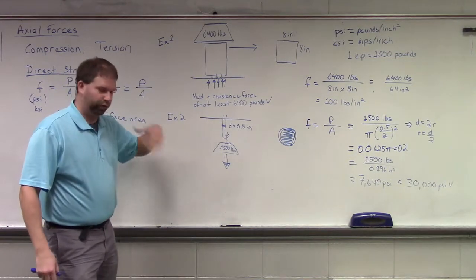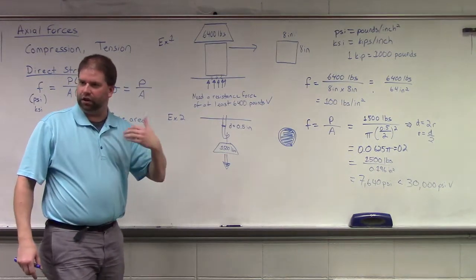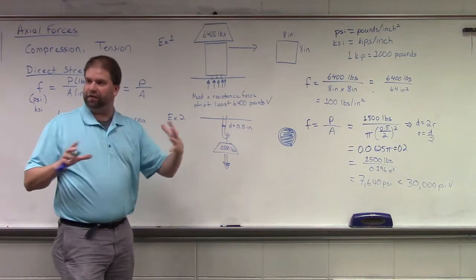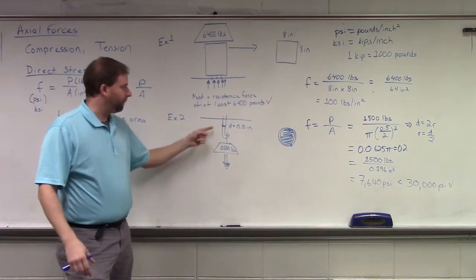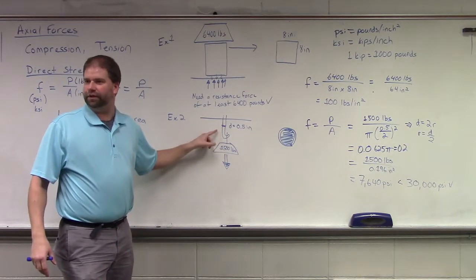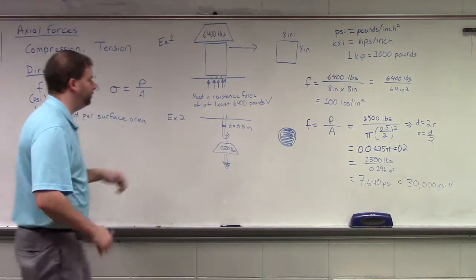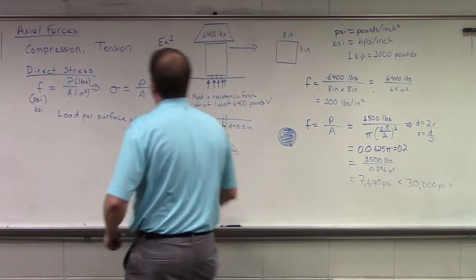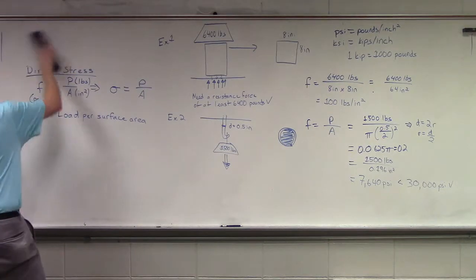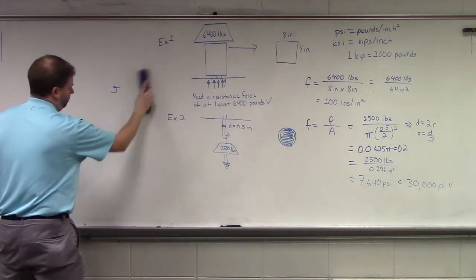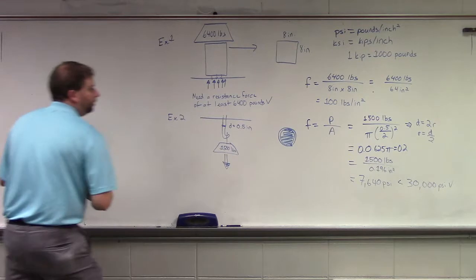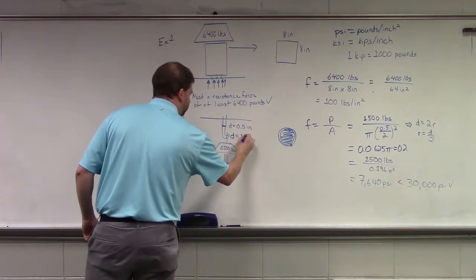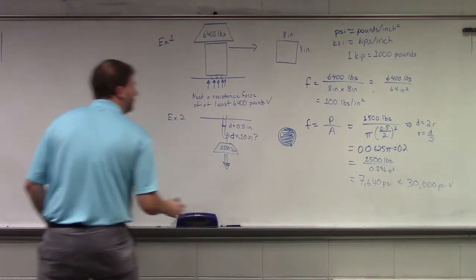Once we get into looking at steel, concrete and wood on their own, we're going to look at what happens as we size these things differently. So what happens if we change the size of this cable? What if we use a 1-inch cable? Is this going to help us? Is this going to hurt us? In theory, it should help. So let's take a look at it. Let's change our diameter to 1.0 inch.